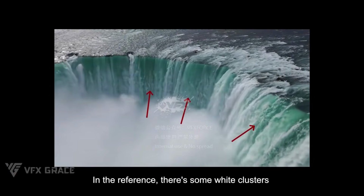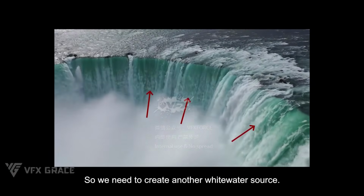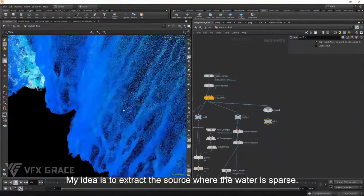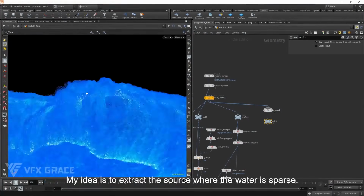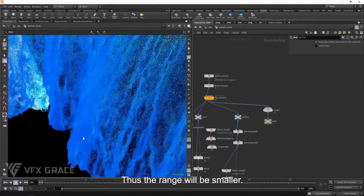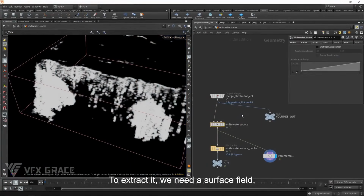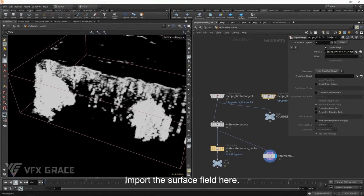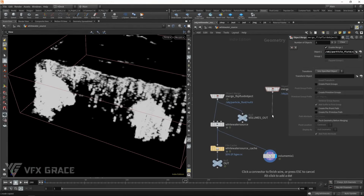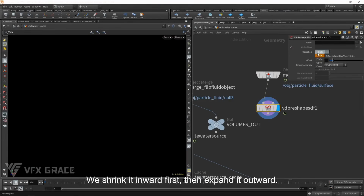In the reference, there are some white clusters when water falls, so we need to create another whitewater source. My idea is to extract the source where the water is sparse. Thus, the range will be smaller. This way, the whitewater won't be too much. To extract it, we need a surface field. Import the surface field here. We shrink it inward first, then expand it outward.